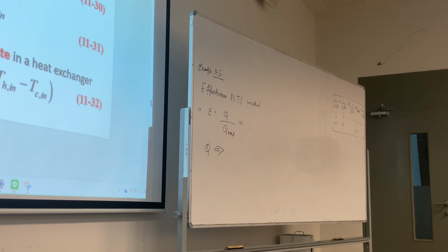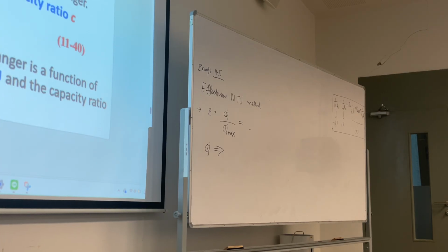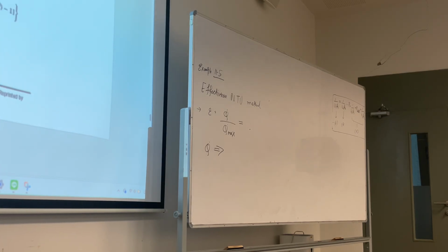This I will write down all these three. And okay, don't freak out after looking this one. So when you are solving the NTU, when you are solving the heat exchanger problem with NTU method, you have two tables. Okay. If the question is asking you effectiveness epsilon, right? So you use these formulas based on what heat exchanger is given.